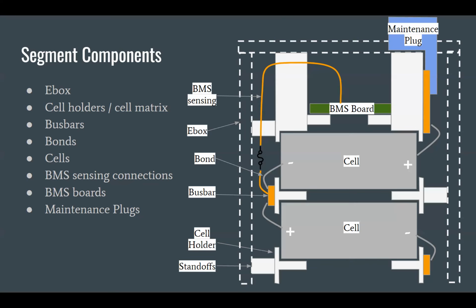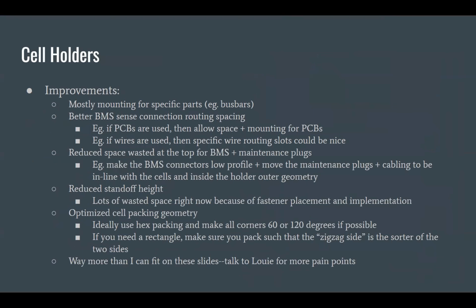to untwist itself. That could be anything from a lock nut to 3D printed things that go around it to make sure it doesn't come loose, to safety wire that goes around it. Make sure that one bolt won't be able to loosen because it'll tighten another bolt. You could safety wire... We literally thought about safety wiring the bolts with nylon. We didn't do it, but we could have. Stupid ideas. But yeah, that's one of the high level things.